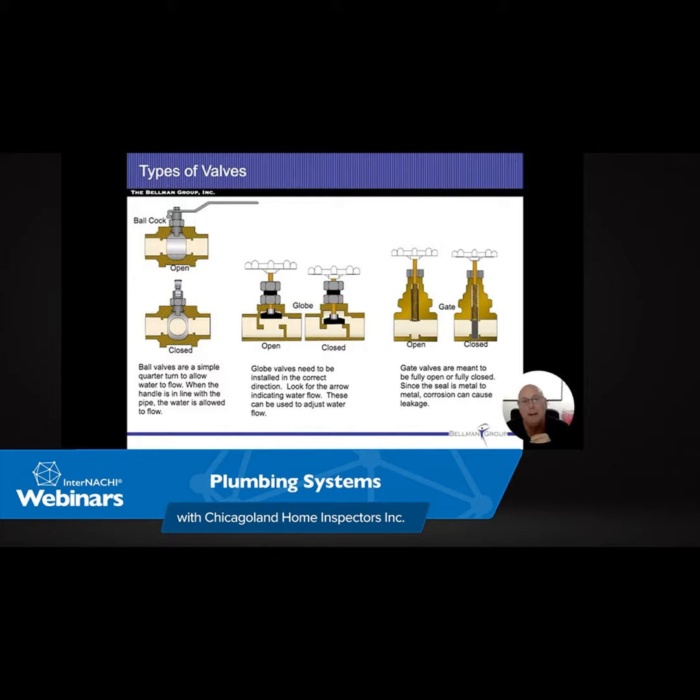But nonetheless, there's 3 layers inside of a tank, all right? So as we're looking at this tank, the wastewater comes in from the left and goes out to the field on the right-hand side. I want you to know the 3 names of the 3 layers. So the sludge is the solid layer, so the sludge is at the bottom. The liquid is called the effluent, E-F-F-L-U-E-N-T. And then the foam that's at the top of everything else, that's called the scum. So whenever we called somebody scum, we were referring to the foam that flows on top of these septic pits, which I don't think is a nice thing to say, all right?